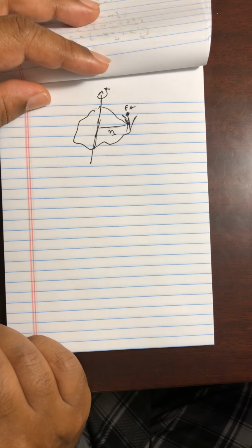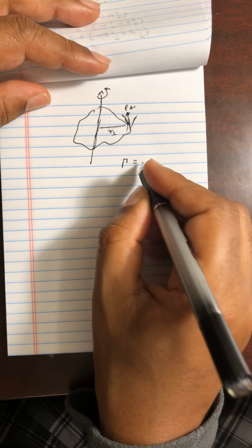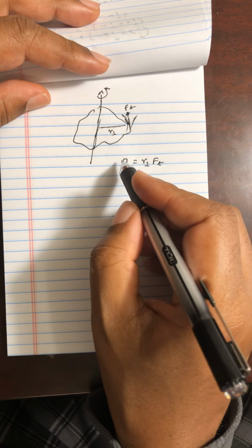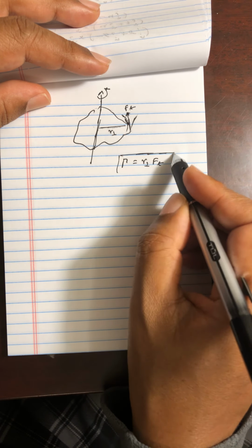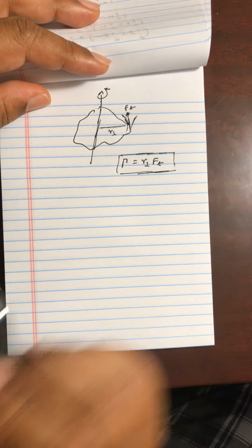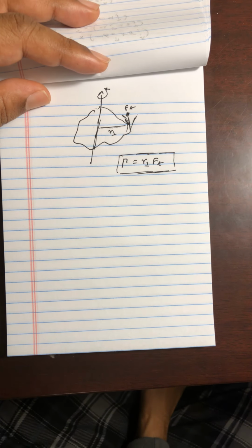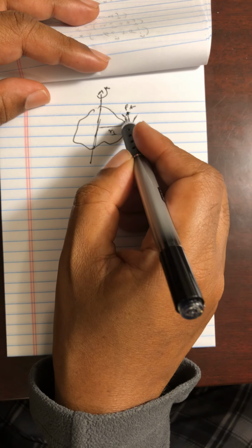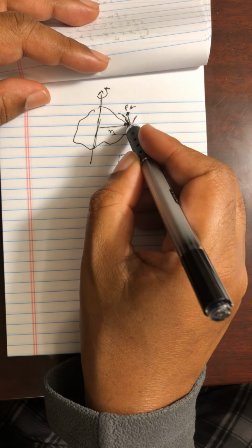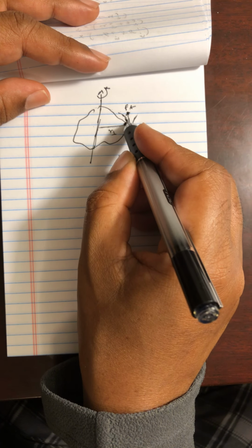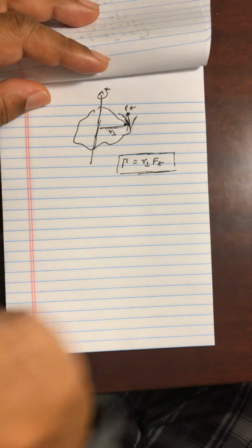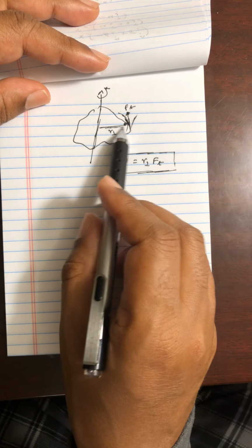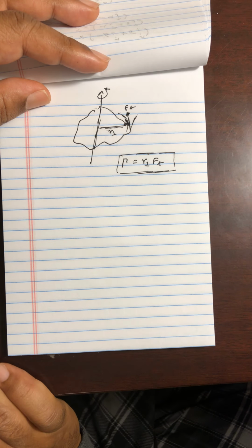this distance over here. So you can say torque is the perpendicular distance times the tangential component of the force. That's how you calculate torque: the perpendicular distance times the component of the force in the direction tangent to the circle. If you take any point over here, it's rotating in a circular path, so you take the component of the force tangent to the circle, and then times the radius of that circle will give you torque. So it is a product of the perpendicular distance and the tangential component of the force.